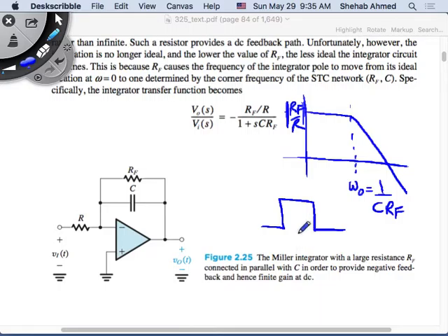That's the question. When I put a square wave without this resistor, the square wave looked like this. Try and keep the gain outside. It was a negative ramp. Now I put the square wave and I'm adding some frequency dependence to the circuit by making this look like a low pass filter, with an omega naught somewhere here. What's going to happen? Obviously, I will not have these sharp rises.